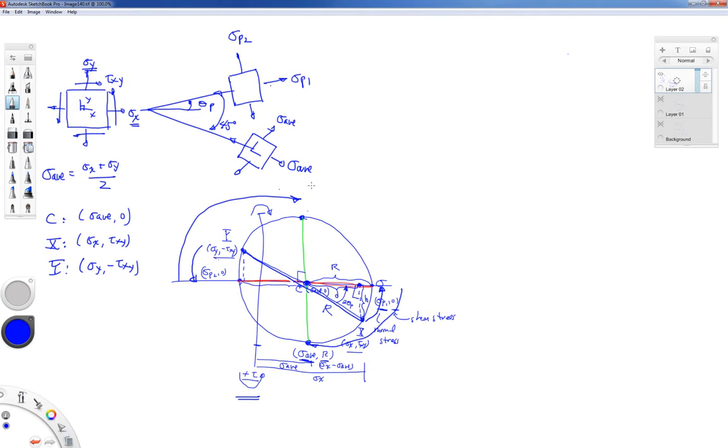Now here's something that I think is the trickiest thing about Mohr Circle. We need to put the maximum shearing stress in the plane on this block. We know the value of the maximum in-plane shearing stress is the radius of the circle, r. But we need to know if the arrow will point up in this direction or if it will point in the opposite direction on that face. If you notice, I'm sketching in my coordinate system as I rotate my block. That's going to be very important.